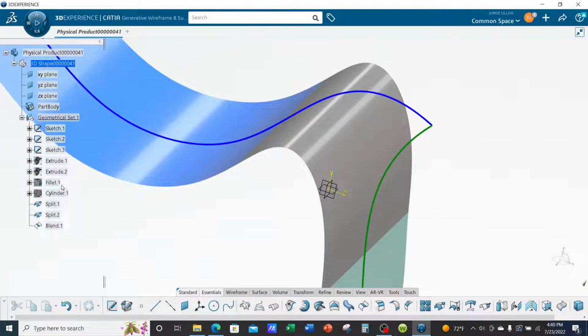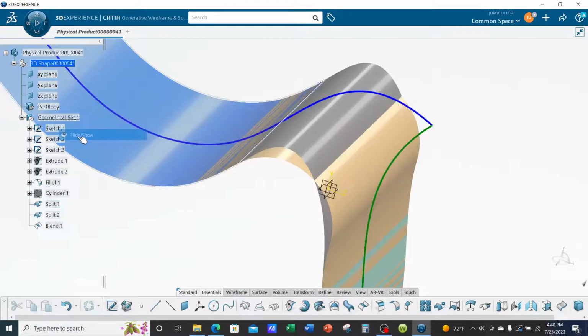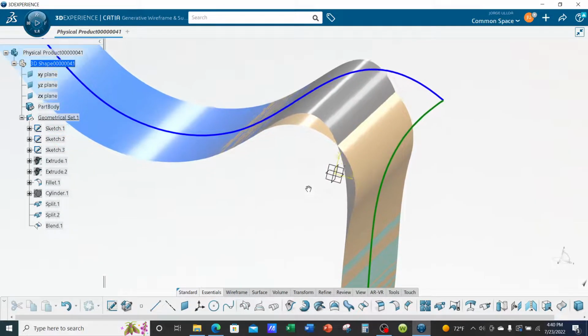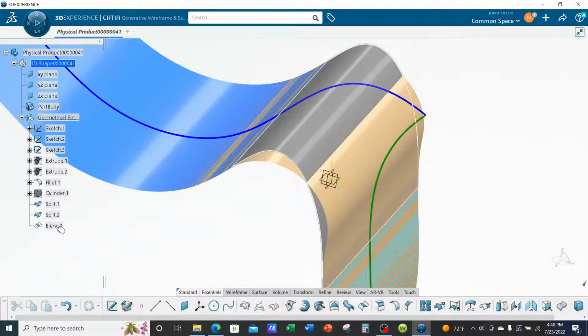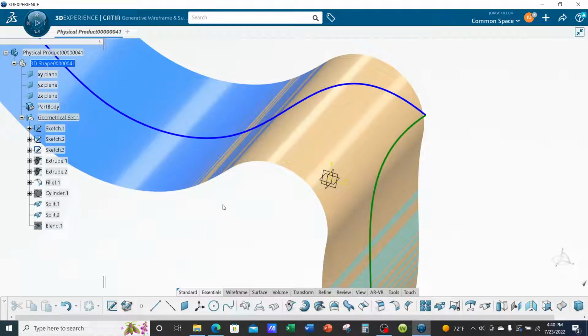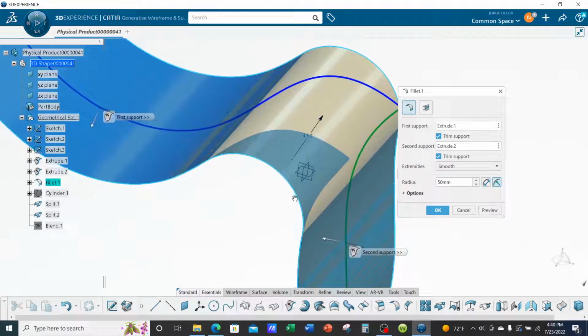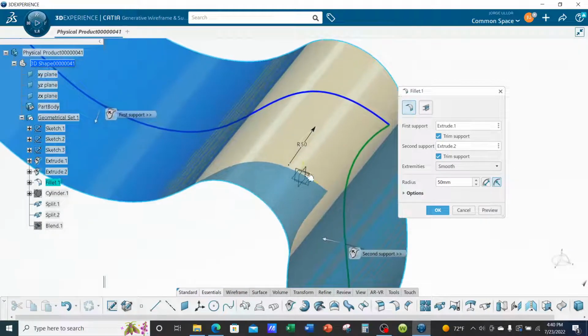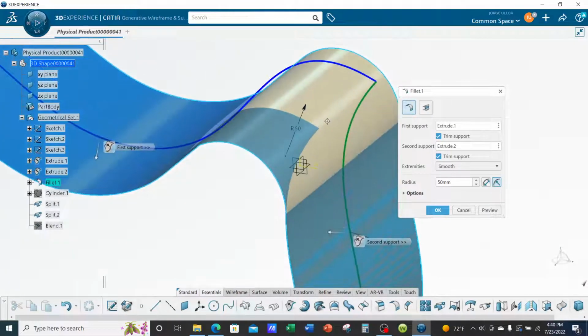If we were to go back to fillet, so here's fillet. Let me turn off the blend for a minute. Okay, so when we did the fillet, double click, it removed what's shown in this vanilla color. It removed the excess because the trim options were on. So we removed the excess from the green and the blue surface and then joined them all into one surface.